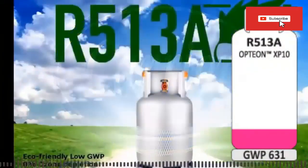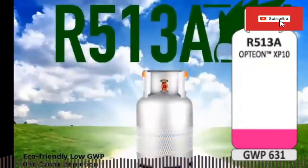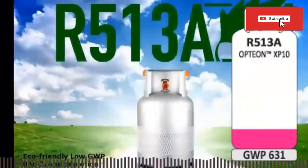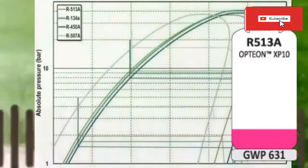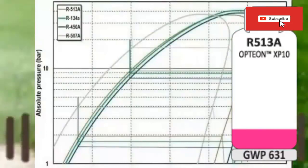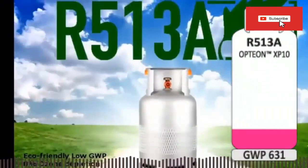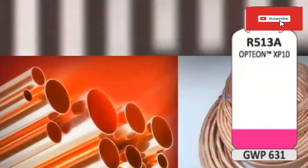11. The higher vapor density of R-513a on the suction side of the compressor results in a higher mass flow rate. 12. When using R-513a, the mass flow rate is increased by about 15%. 13. Depending on the diameter of the pipes, a higher mass flow rate causes a significant increase in the pressure drop, in some lines, and an increase in the compression ratio of the compressor.